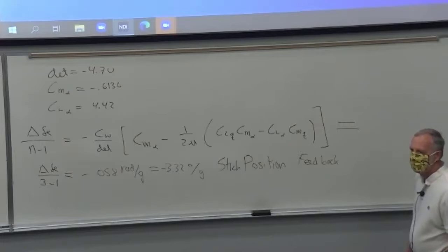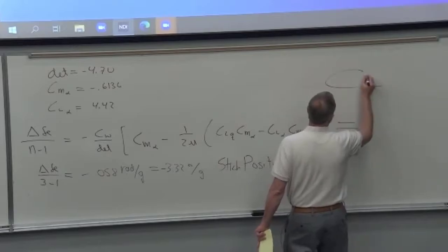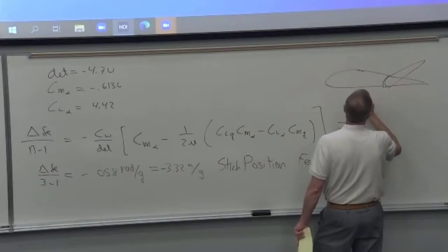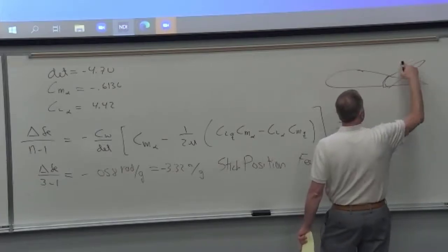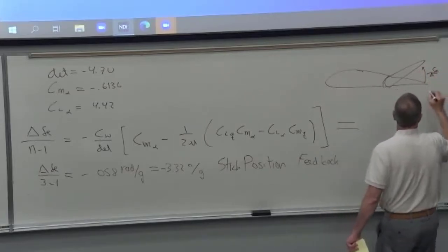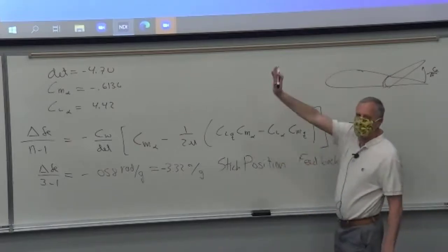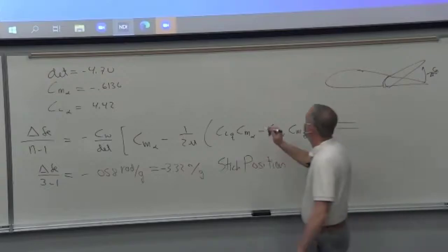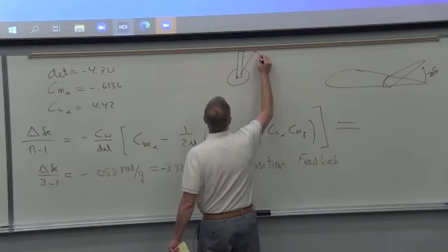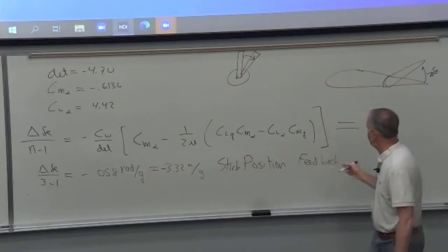Yeah, because that means that you have to pull on the stick, right? Let's draw the picture again. There's level flight. We want to pull on the stick. That's a pitch. If the elevator goes negative delta, that's the direction to cause the nose to pitch up, and that's the motion you're doing when you're doing the pull-up. And that's connected to the stick, my stick's kind of short, of moving backward like that. So yeah, this is good feedback.